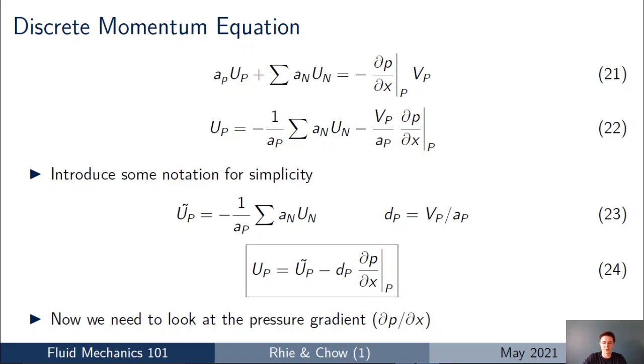And this allows us to arrive at equation 24, which I'd like to emphasize is still a representation of the discrete momentum equation. We haven't done anything different here. We've just discretized our momentum equation for the mesh, and that's the momentum balance, which you can see there. What's going to happen is the convective and diffusive fluxes into the cell are still going to balance the pressure gradient across the cell. At this point, what we've done is fine and consistent. We're not going to be generating any checkerboard oscillations at this point, but now I'm going to start to show you how equation 24 can show us where the checkerboard oscillations start to arise from and why you might need to consider something like Rhie Chow interpolation.